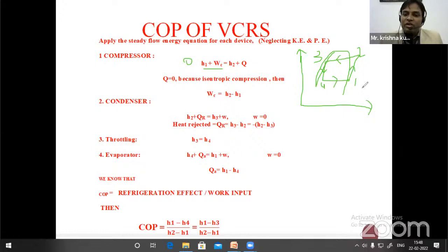So here we are talking about the compressor. This compressor is fitted between the 1 to 2 process. At the initial step, or the inlet of the compressor, we have the energy at H1. When we are giving some work input in the compressor, it compresses the refrigerant basically. So we need to add WC, the compressor work. Then it reaches point 2, where we can define that level of energy, which we represent with the help of enthalpy. This axis is P, and this axis we have H, the PH diagram. So here also the H2 you can represent here.